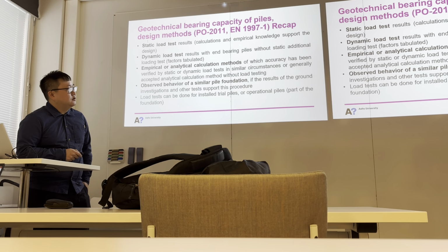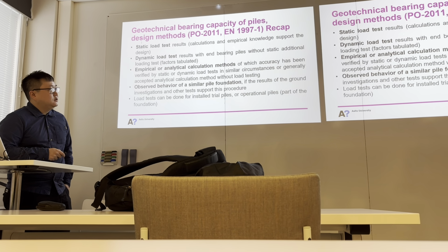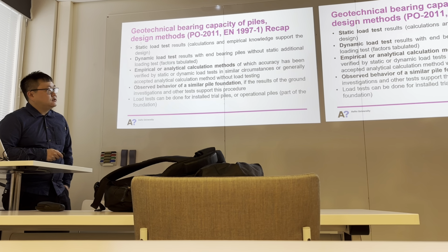The last one is observing the behavior of similar pile foundations. If we have a design project for piles that is similar to previous cases, we can use the results of ground investigations and other tests to support our design procedure. Another thing to remember is that the load test can be done on already installed trial piles or operational piles, which are part of the foundation.